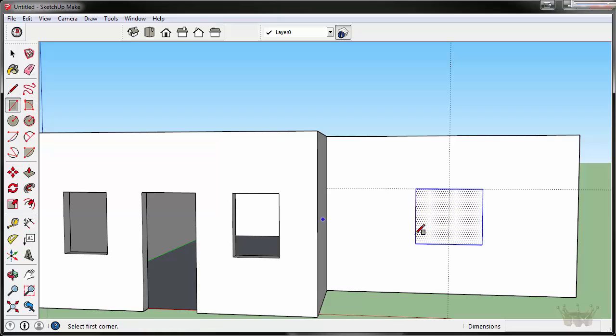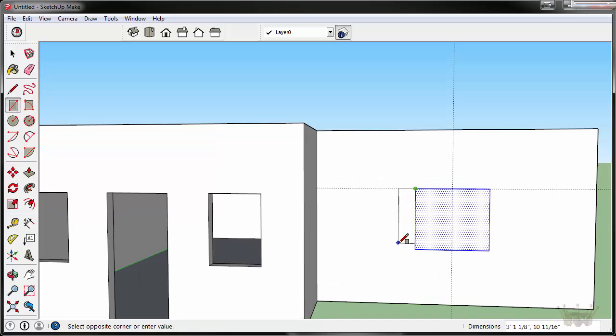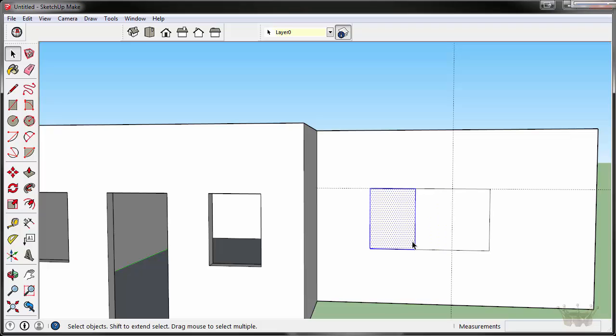And now create 2 additional windows to the right and to the left for a distance of 2.5 feet by 3.5 feet. Make sure you're entering the numbers in the correct order using feet and inches, as I just didn't do there. So I'll Control Z it, and I'll enter it the opposite way, which is 3.5 feet by 2.5 feet. And with 2 clicks to select just this one, I'm going to execute another copy move and bring it over to the side.